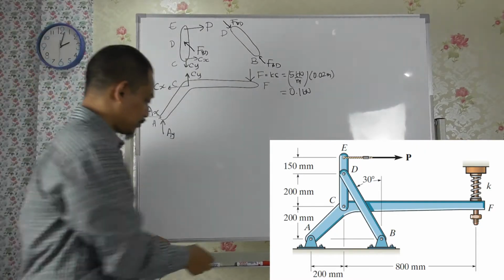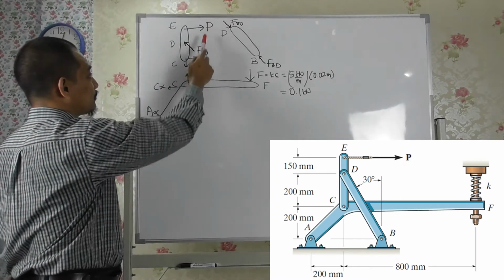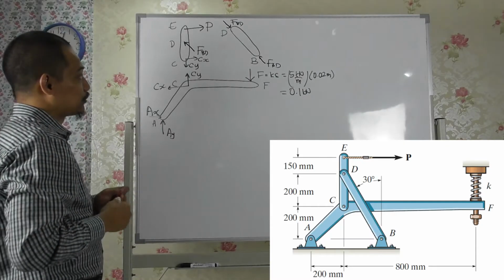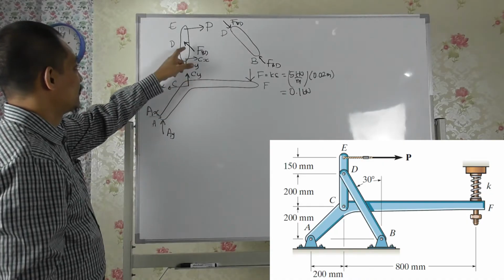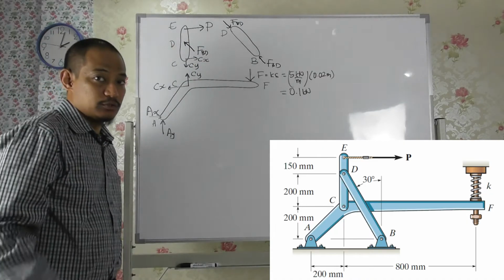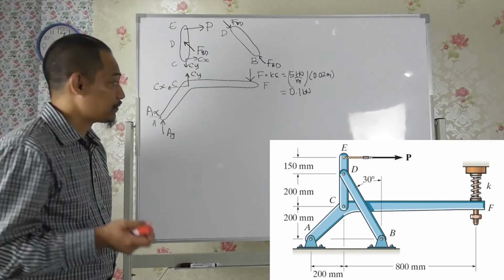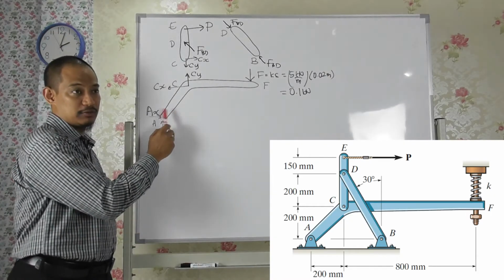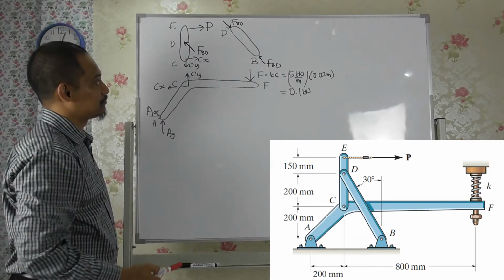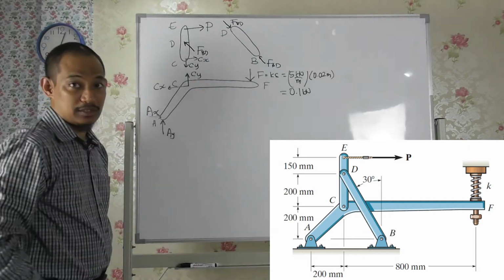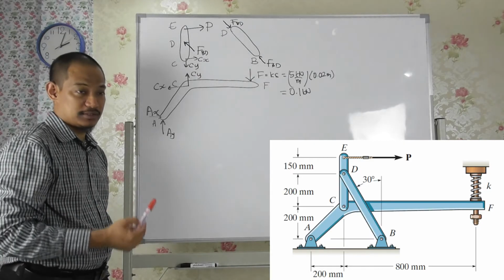Okay, what else? So all the forces are here. So this is known, and the rest are unknown. Right? So how many unknowns do we have? 1, 2, 3, 4, 5, 6. Right? So if you have 6 unknowns, you can solve if you have 6 equations, right? So basically you have this free body diagram here, hence you have 3 equations here. You have another 3 equations here, right? This one is not useful because there's nothing that can be calculated there, right? So you have 6 equations and 6 unknowns, so you should be able to solve.